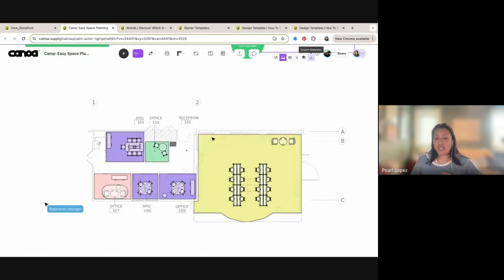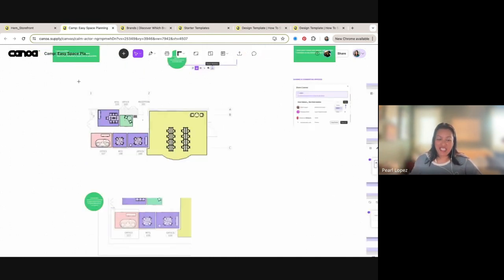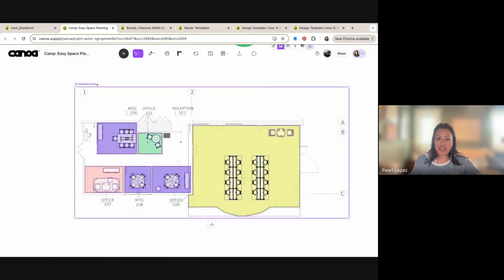I want to just bring it into CAD because I do need to submit something. I'm working with a team that only uses CAD. Obviously, I have to submit my drawings. So no problem. You can just take all of this. You're going to drag select everything. You're going to see up here the number of items. So when you drag select, basically what you're going to do now is export this into another DWG version. So you can take what you've drawn here and bring it into CAD. You have to drag select because what you want to do is take everything that I can see here.